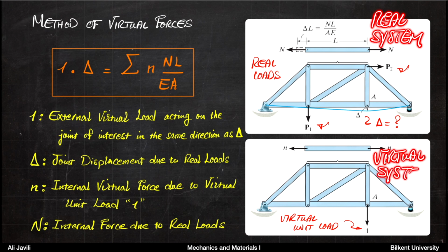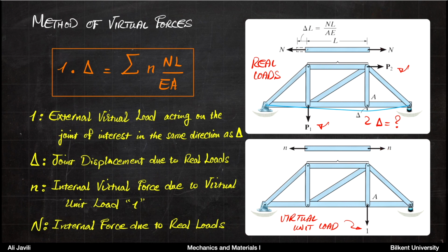On that virtual system, you apply a virtual load, and we usually apply a unit load 1 for simplicity, but it doesn't have to be 1, exactly at the point and the direction that we want to calculate the displacement.